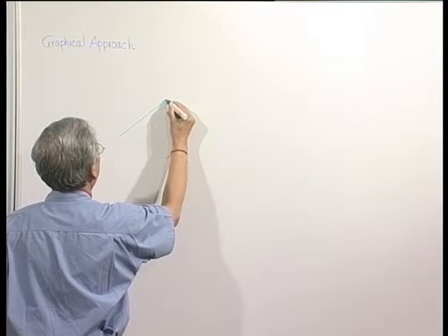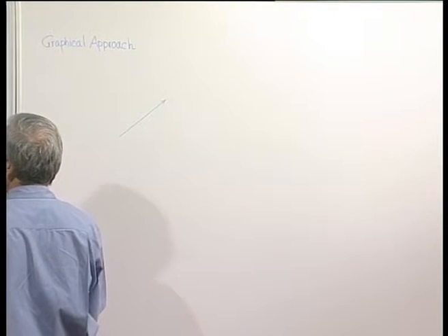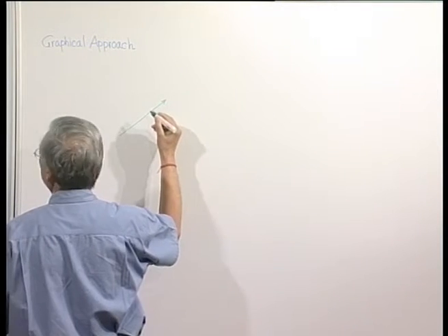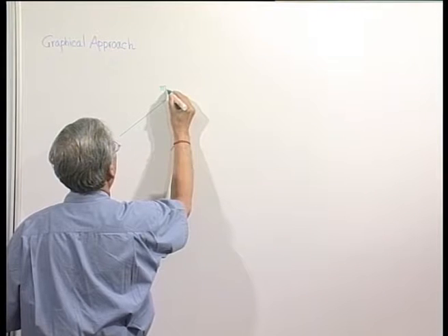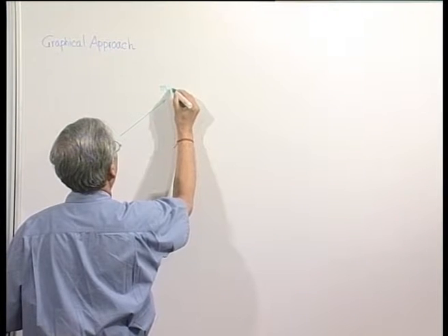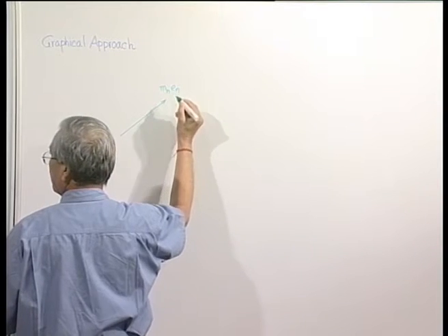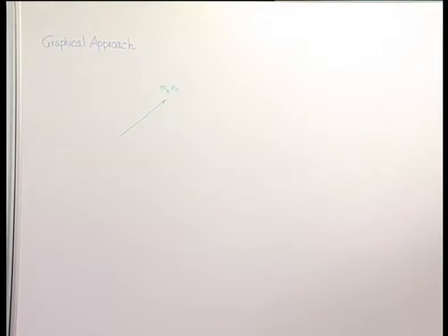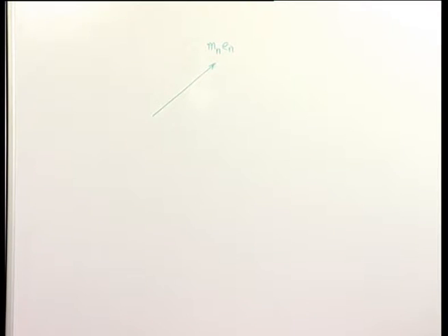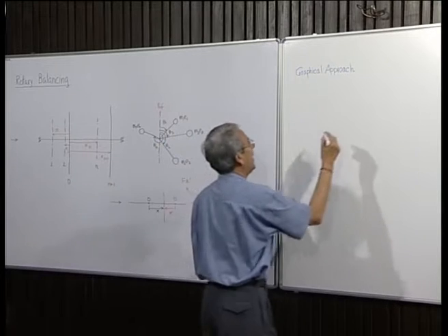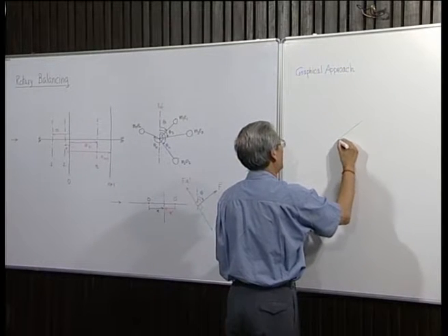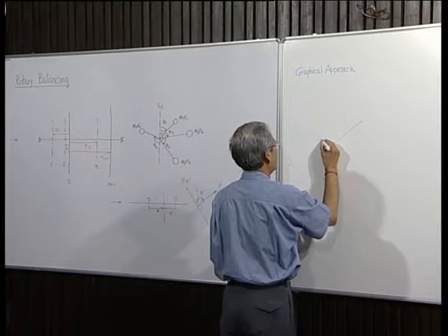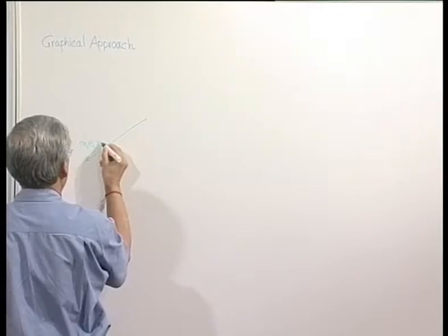So, this will be the moment due to the unbalance in the plane, let us start from 1. Now, since plane 1 is on the left hand side, x is negative, we will have the first moment opposite to this, because x1 is negative.